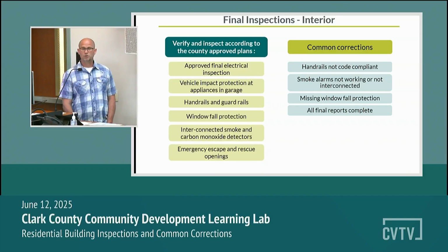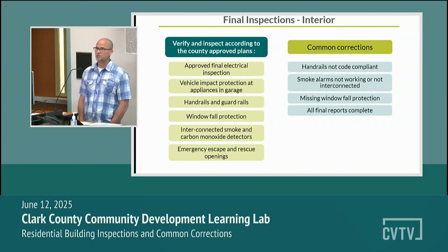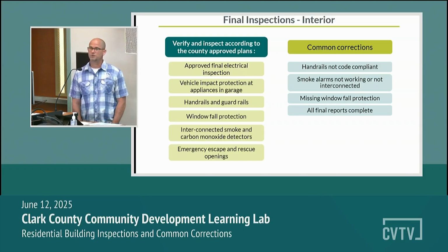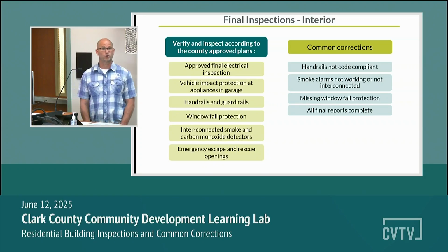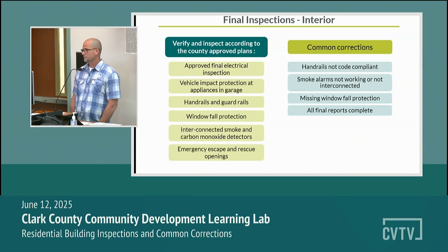Now back to smoke alarms. At the framing inspection, we checked to see that you had those boxes in place. Now we're going to check to make sure that you put the smoke detectors, the carbon detectors, the heat detector, where they needed to be, and that they all are working. They're all interconnected. We're going to push the button and make sure they're all working at this point as well.